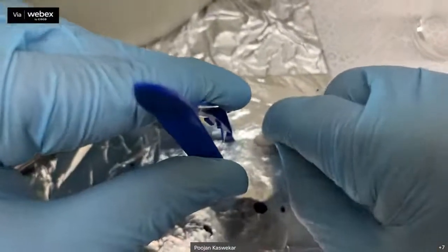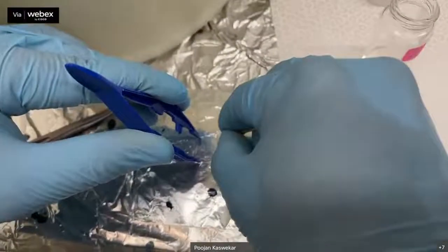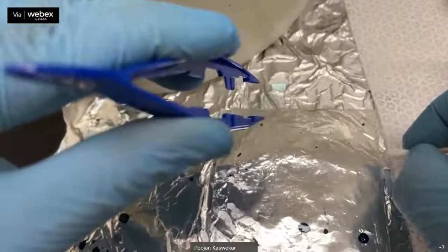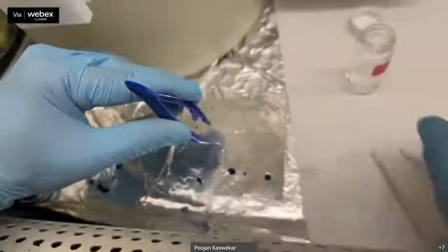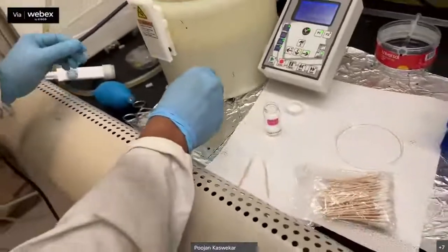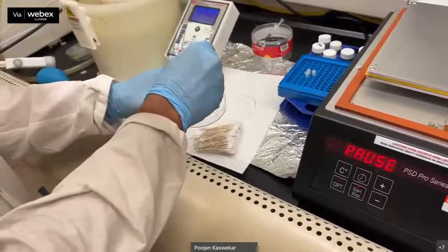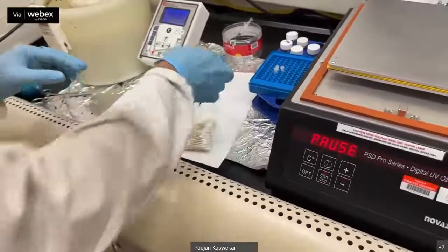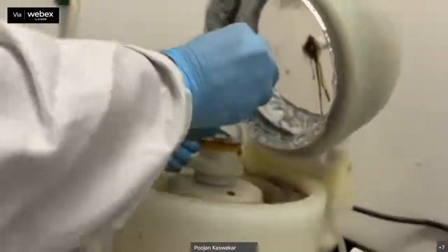And then for etching on the right side of the sample, do it very carefully, and you need to etch it steadily and use some force to keep it etched out, and you try it out with another. So after finishing that, we can put them on the petri dish, and then we can do another sample. Usually you can also do the etching while you are waiting for the spin coating of the next sample.